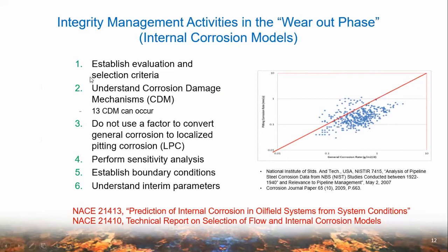First, you establish the evaluation and selection criteria. That is, understand what data you have and what you want to get out of the model. Second, you understand your corrosion damage mechanisms, CDM. 13 CDM can occur during operation internally. Prominent among them is localized pitting corrosion.